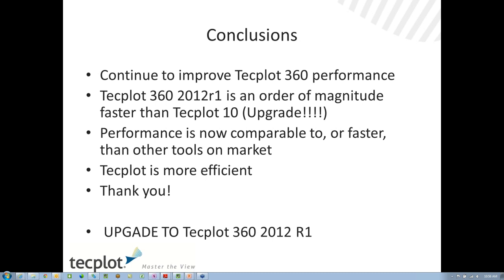Another question had to do with memory usage by Tecplot. There's two things on that. People often will look at the task manager and say, okay, Tecplot 360 is using this much RAM. But if you go into Help, About Tecplot, it'll actually show you how much it's actually using. And that's probably a good thing to look at. Depending on the size of your model, we get into that data I/O when we do load on demand. If you start to run into limitations on your memory side, we'll start to unload data as necessary. So it's a complex problem. Someone had asked, how do I increase it?